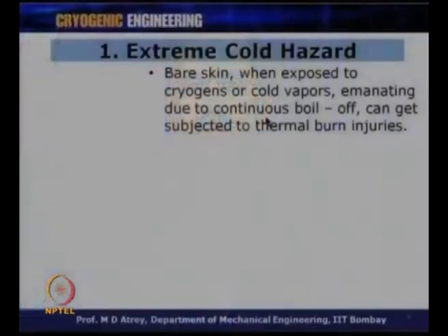We know that bare skin, when exposed to cryogens or cold vapors emanating due to continuous boil off, can be subjected to thermal burn injuries. You must have dealt with this when you go hiking in the Himalayas, for example, where you can get frostbite. Frostbite is nothing but your skin, your hands or your legs, being subjected to cold for a long duration, and this can lead to fatal accidents. So, bare skin exposed to cryogens or cold vapors can cause thermal burn injuries.